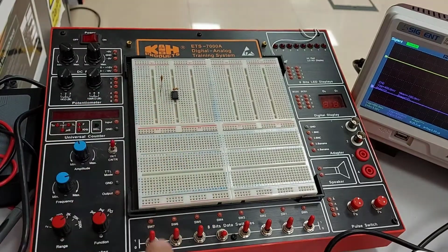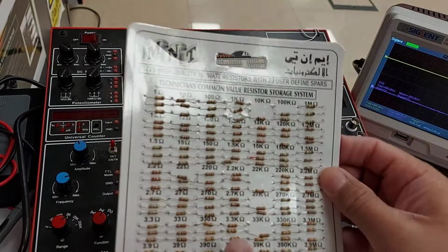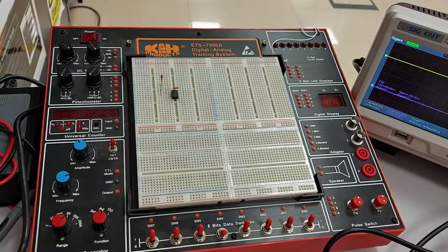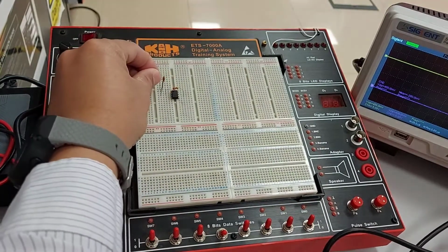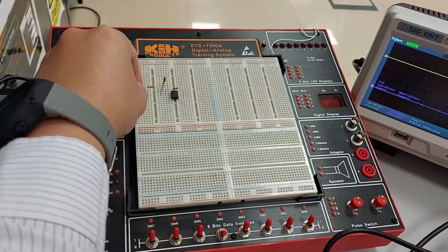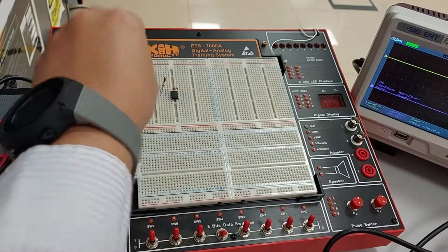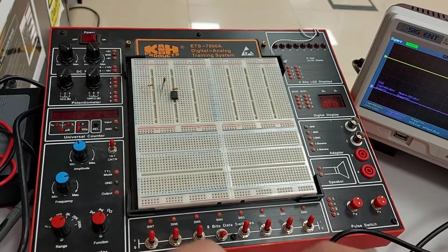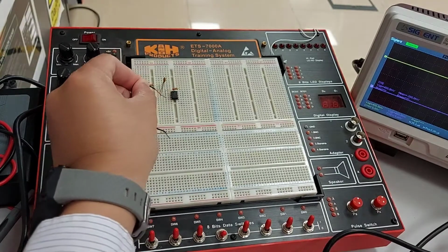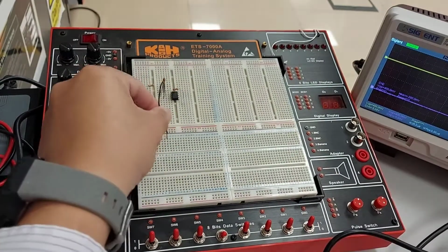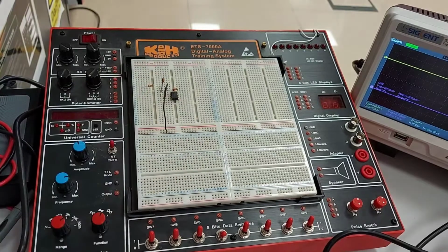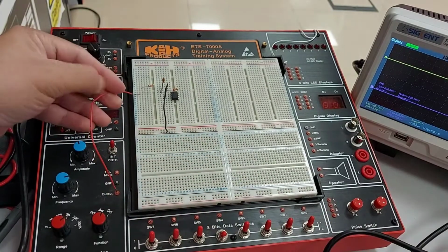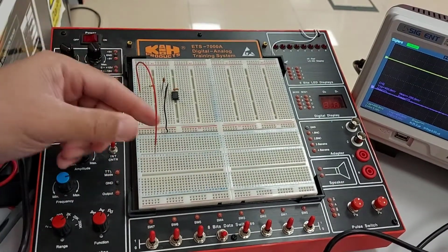And then a 2.2 kilo ohm. So look for the 2.2 kilo ohm, there it is, red. From the capacitor, connect it through here to this point. Number 3 will be directly connected to the ground, so 1, 2, 3, connect it to the ground like that. You also need an output from the function generator. Connect it to the 2.2 kilo ohm resistor.